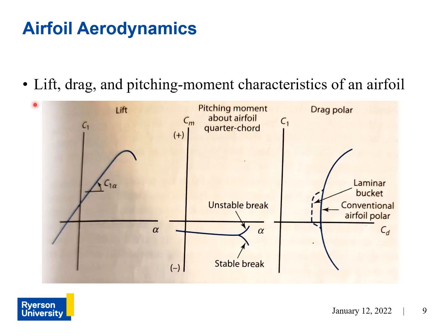So the three main aerodynamic characteristics of an airfoil that are worth paying attention to are lift, drag, and pitching moment. When looking at airfoil data, it's typical to see three plots, which show the variation of the lift, drag, and pitching moment at different flight conditions. It's interesting to note that lift, drag, and moment are expressed as non-dimensional coefficients.